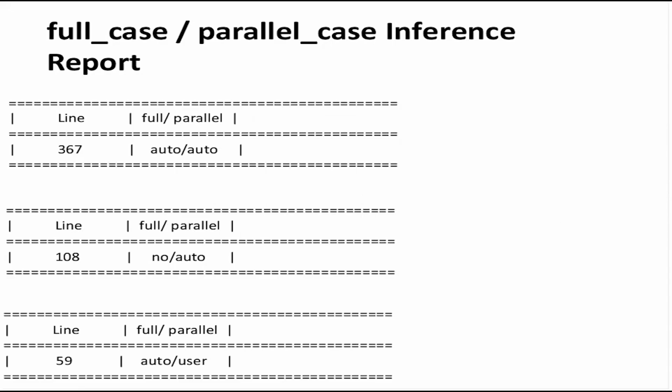Because of the usage of synthesis directives, since synthesis directives are ignored by any other tool, any simulation tool, it might cause simulation synthesis mismatch. And simulation synthesis mismatch is not a desirable condition. It is difficult to debug. You have to again review your RTL code and so on.